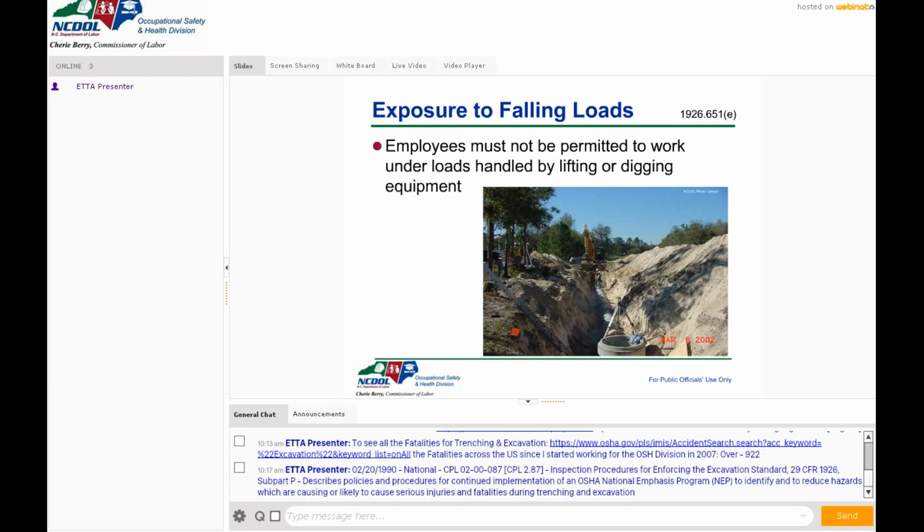And along the edges of this bank right here, you can see the ground is sloped back some, but what you do notice is the material can very easily roll down in there, or if a piece of equipment is sitting something down into the site, then you need to be clear of the area where it's going in case something happens and they accidentally drop the load. So you got some other additional things you need to pay attention to here.